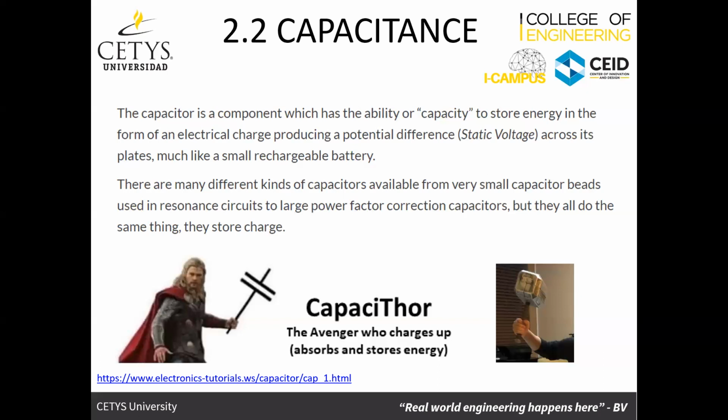The same thing happens with an electrical circuit. Inside an electrical circuit, there are capacitors. These capacitors get charged up when the circuit is connected. Once we disconnect the electrical energy, the energy that's stored doesn't dissipate instantly. It takes time to dissipate. So you might have a device that's connected and working, storing energy in its capacitors, then you disconnect it and you're assuming that there's no more electrical energy in it.